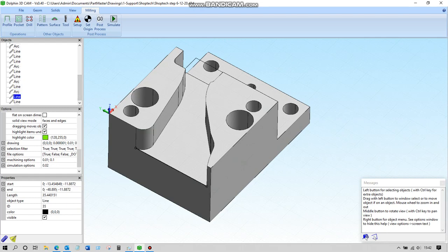If we get to that line there, then that's at X0 because our triad here is at the X position. So if we make that say minus 12, that moves that point, and then the other end here, make that minus 12, and that moves that line. Then this line here, we want its start point to be minus 12 as well. Okay, so that's done that, but we're now missing a segment in here. So what we need to do is draw a line into there.